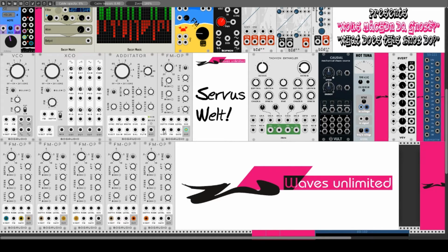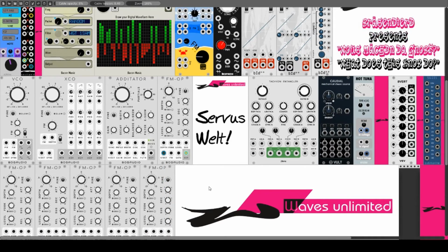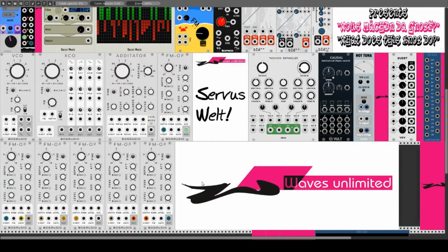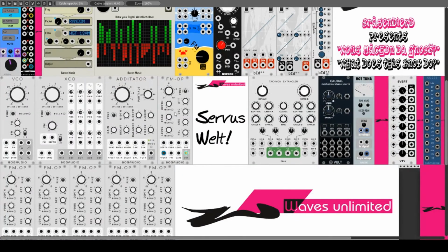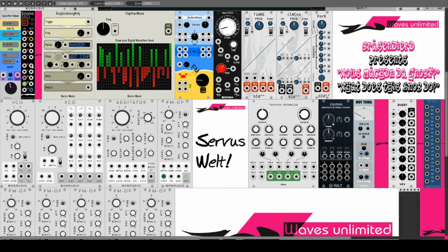Only so much at this point: the arrangement of the operators in series or parallel and the strength of the influence of operators on each other determine the algorithm and ultimately the sound. The depth and CV controls can be used to influence the input of an external FM signal on the FM input and the internal feedback of an operator, as well as the strength of the output signal, adjustable with the level knob.